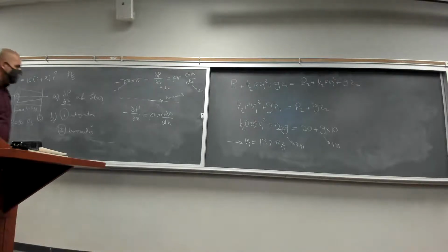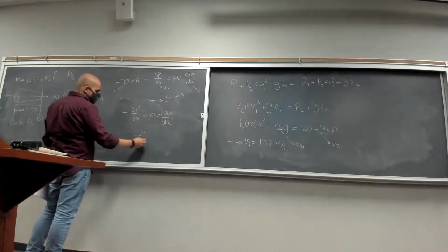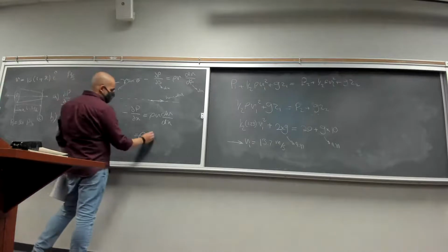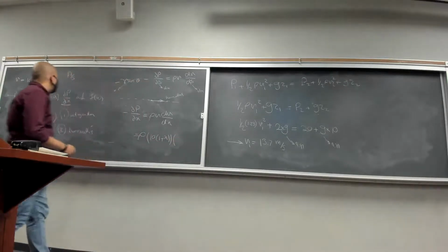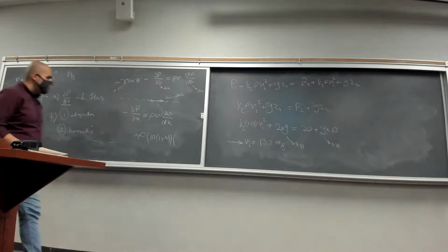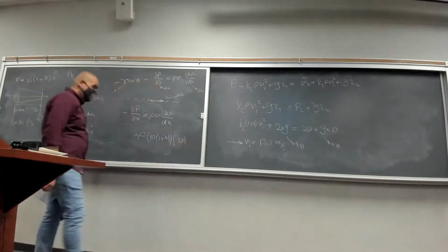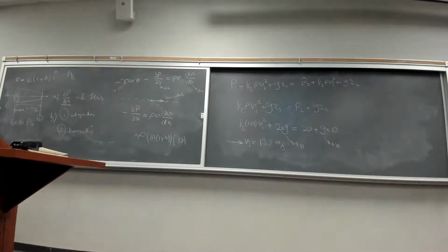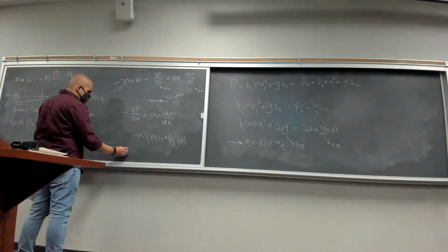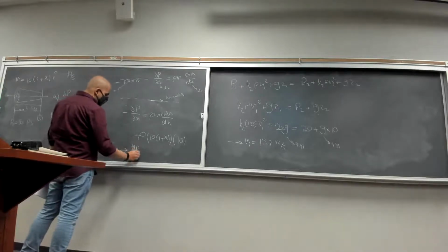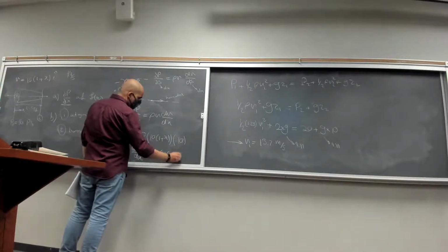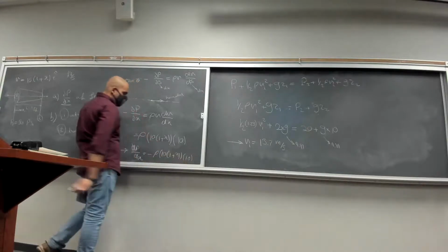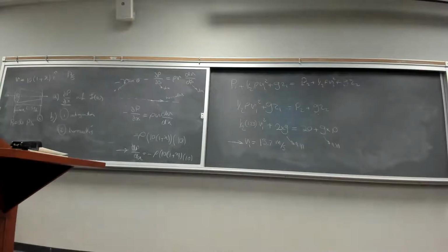Okay. So let's put all the values in. Your velocity is going to be 10 multiplied by 1 plus x. Your derivative of velocity with respect to x is going to be 10, right? And that's it. That's your pressure gradient. Of course, you have to move the negative sign to the other side. Your dP dx is going to be equal to negative rho multiplied by 10.